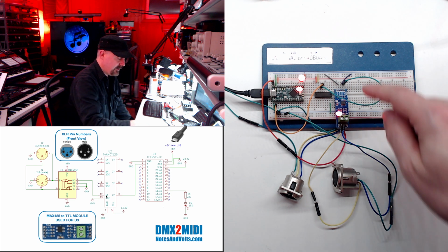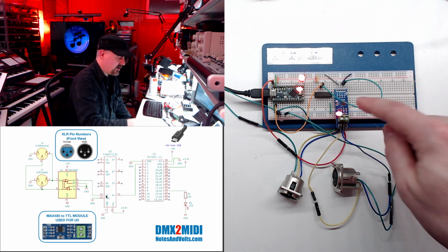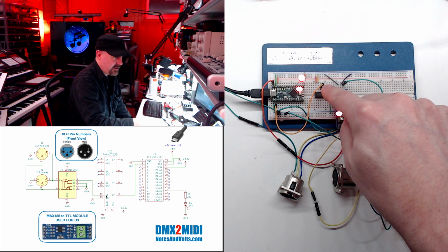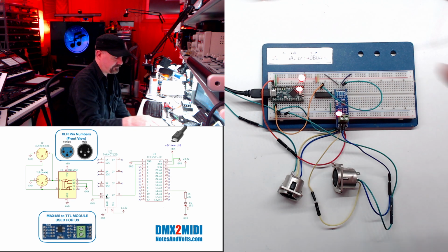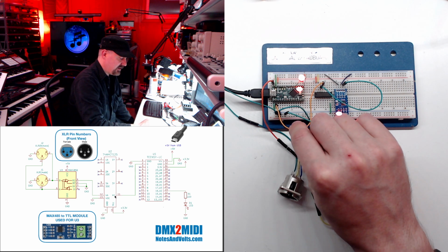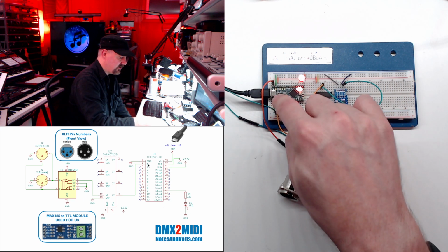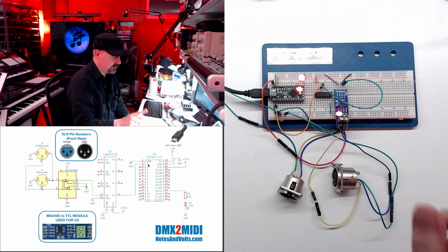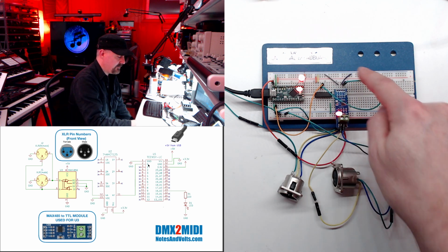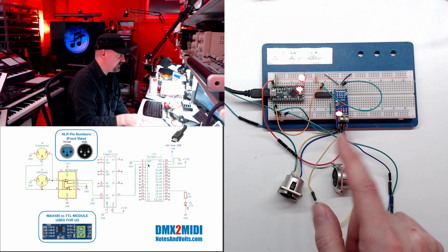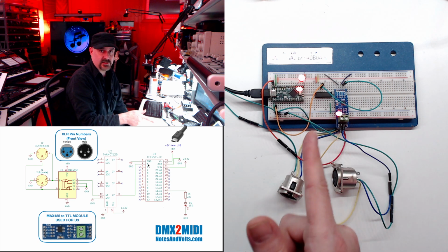So we're going to take the output from our driver board, which is 5 volts, and that's going to go into the A pin on our buffer. Now the Y pin is the output, and there it is right there, and I can take that and run it up to input 0 on my Teensy. So there's the wire running to input 0. So remember, we've got 5 volts coming into this chip and 3.3 volts coming out into the Teensy, which is going to keep our Teensy safe.